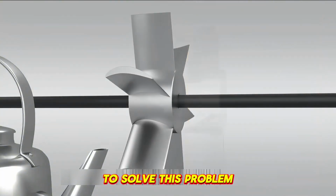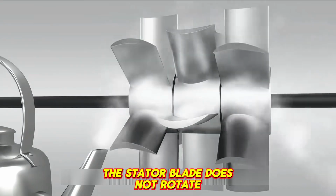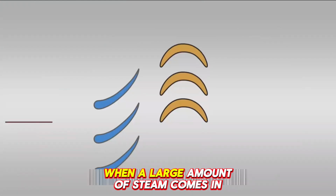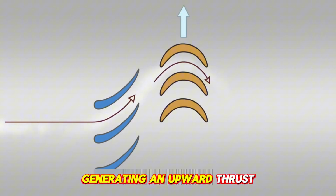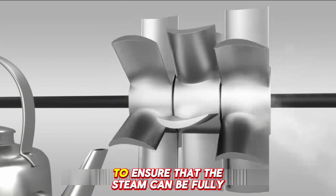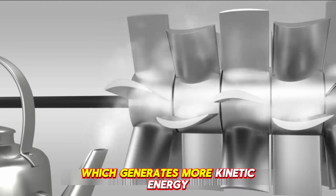To solve this problem, we can add another stator blade and a rotor blade. Among them, the stator blade does not rotate. It is only used to change the direction of the steam. When a large amount of steam comes in from the side, it hits the stator blade. The steam changes direction and then comes to the rotor blade, generating an upward thrust, driving the rotor blade behind it to rotate along. To ensure that the steam can be fully utilized, we can add more rotors and blades, which generates more kinetic energy.